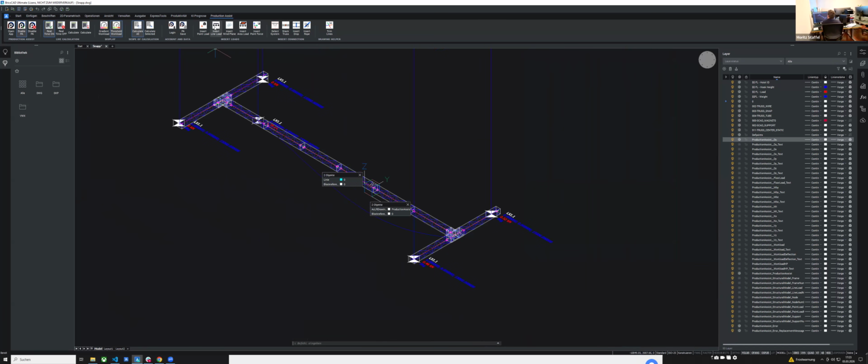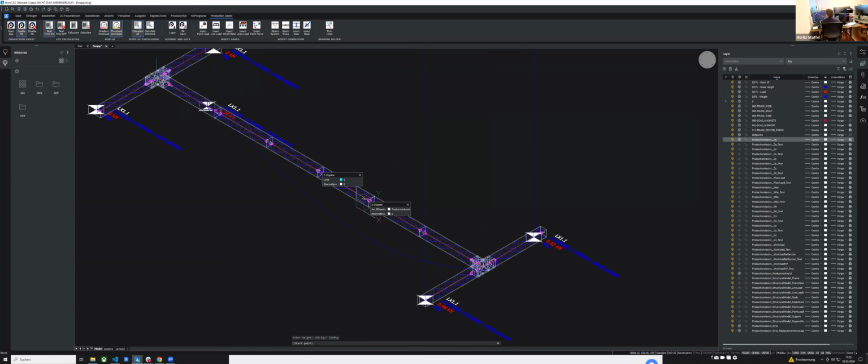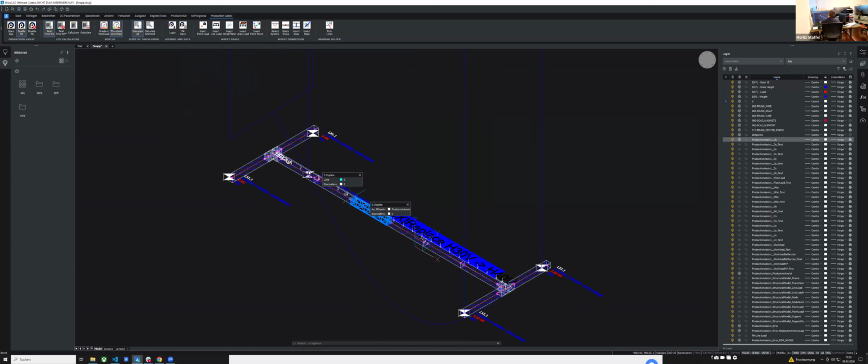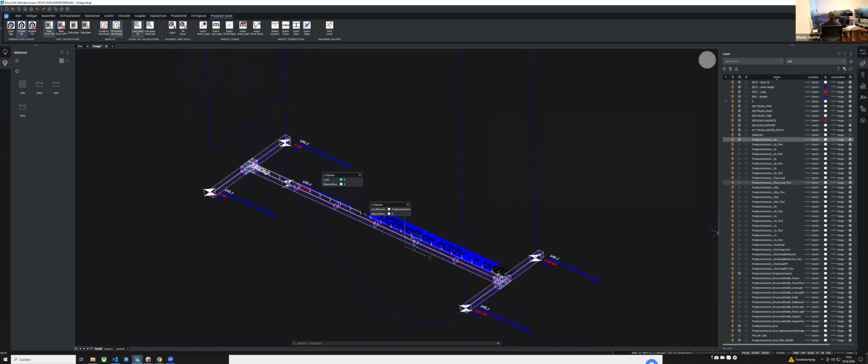What we've also added in here, for example, are tools to insert line load. If you click on here, it asks you what should be the name of the line load, the layer of the line load, and the total weight. So you say like 1,500 kilograms, pressing OK. And then you can say the start point should be here, the end point should be here. When you're done, it automatically adds this line load in here. And because there's so much load in here, it basically lifts the other thing to the side. The results in BricsCAD are also shown in here.